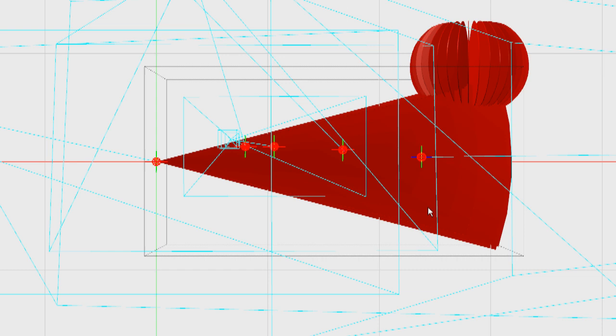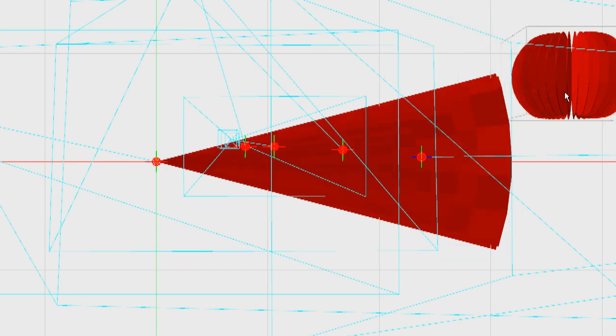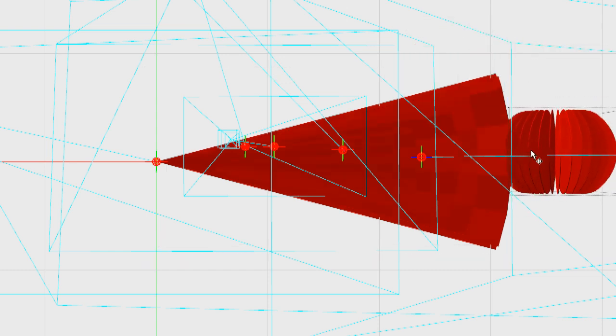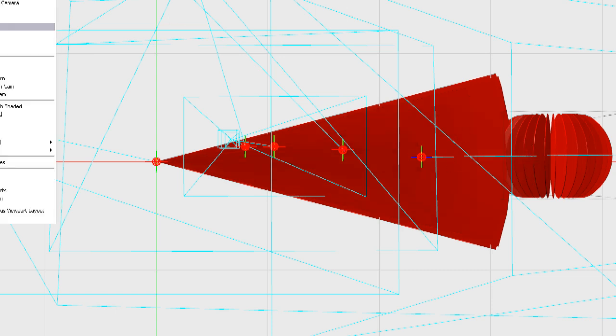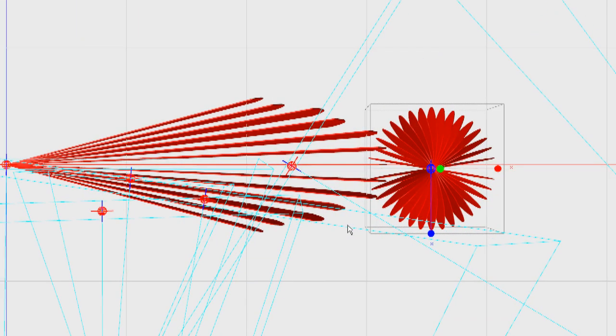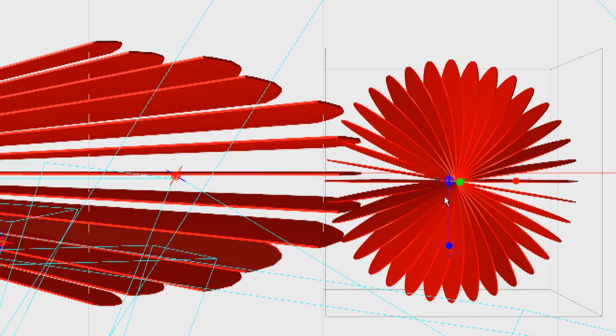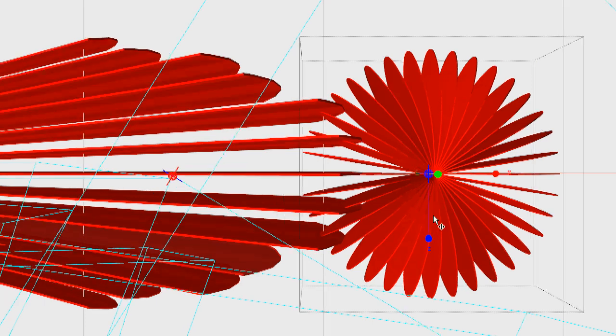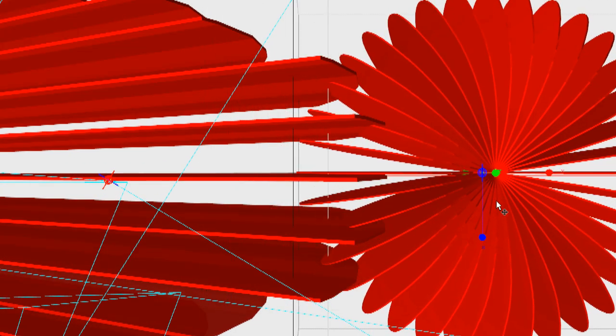So this is even more important, that you make sure that this antenna is pointed directly at your plane. And again, this is a linearly polarized antenna, i.e. it's either vertical or horizontal. So if we look from the top, we can see the pattern here is in a vertical fashion. So, as long as we maintain this range and orientation, we've got a brilliant signal.